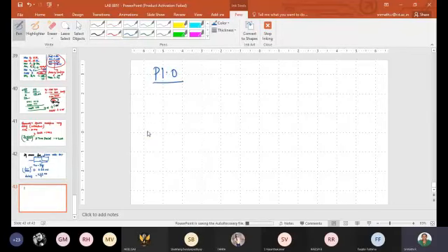Let me use instructions. I need to calculate the count, but before that, let me finalize which instructions you can use. Let me load some count value: MOV, using register R2 as my counter, loading an immediate count value. Let me name it N for the time being. And then decrement this count: DJNZ, decrement and jump if non-zero.